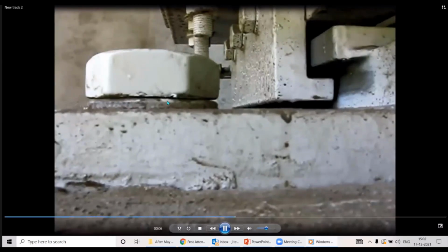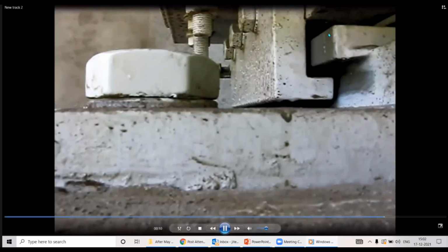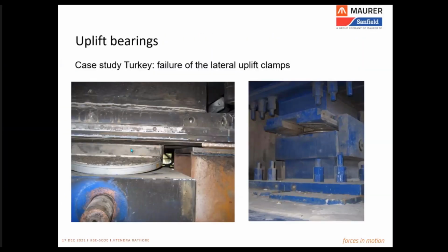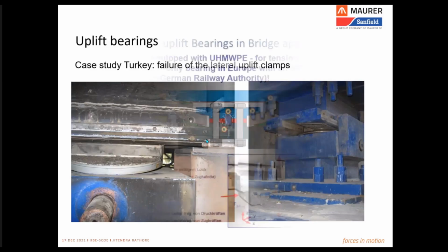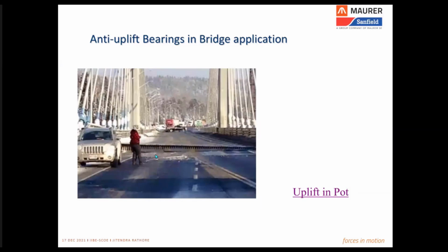And when this happens repeatedly over the period of time, it raises fatigue issues, and at some point of time, the bearing system gives up. It gives up like this because steel always has a fatigue issue, and when you have a repetitive impact loading cycle on the structure or on the steel component, after a certain period of time, it may give you a fatigue failure. And when such a thing happens, you could imagine the catastrophe that it could create.